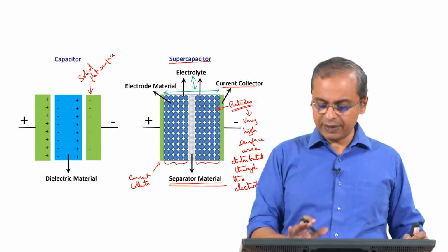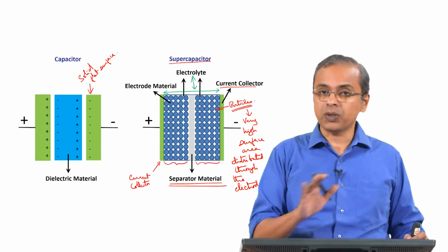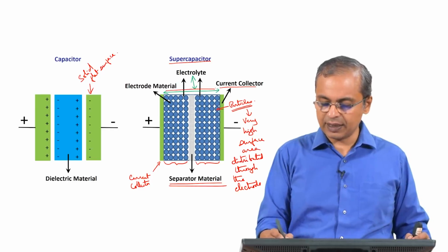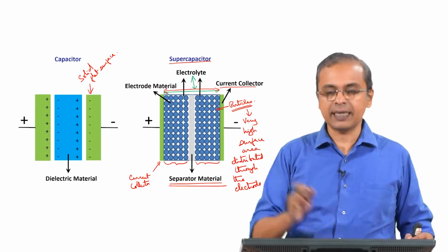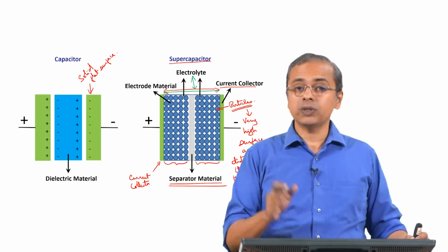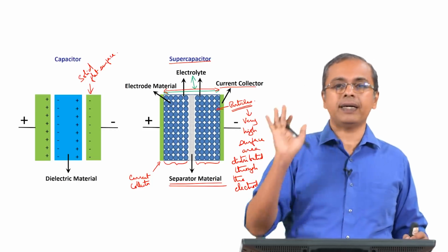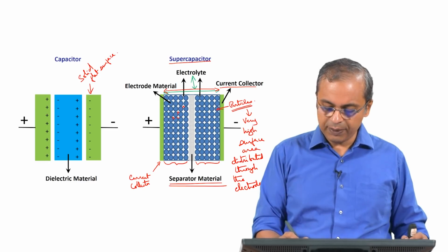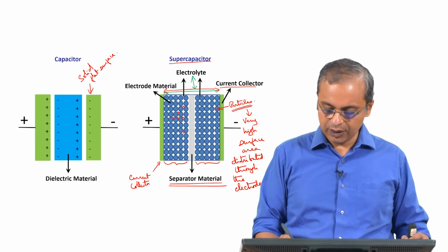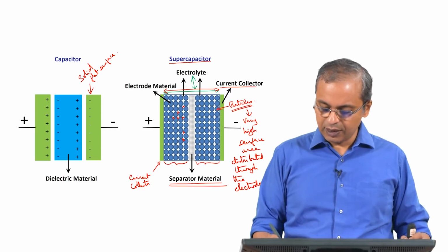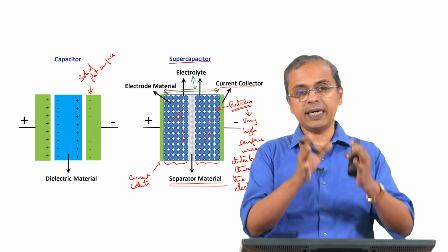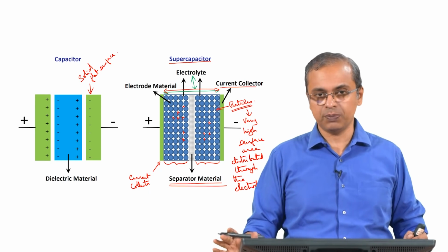We will talk about the charge, but anyway these particles are present, and there is an electrolyte that is present. That electrolyte is present over the entire extent of this region that I just marked here, between this current collector and that current collector you have electrolyte. So, this electrolyte actually penetrates into these particles. All the gaps that you see here are all filled by the electrolyte everywhere. Even whatever gaps you see between the particles are all filled by the electrolyte. So, the electrolyte permeates into this porous structure.